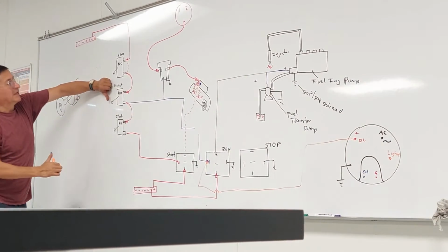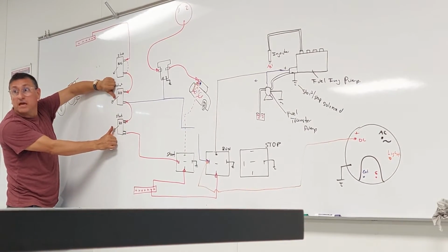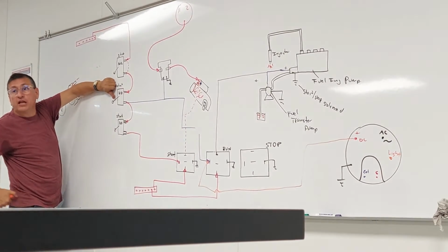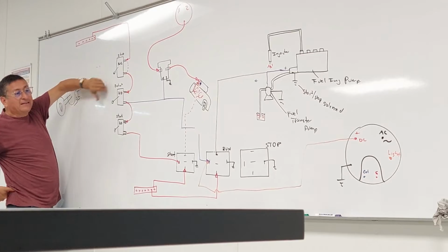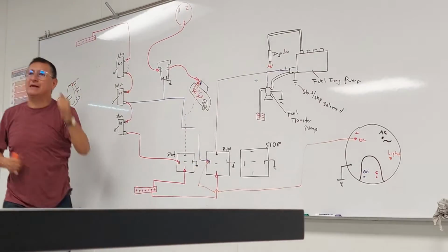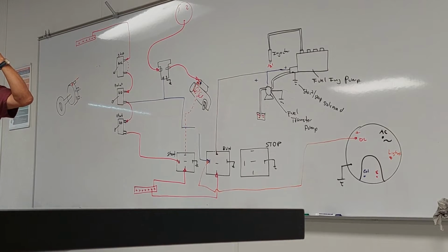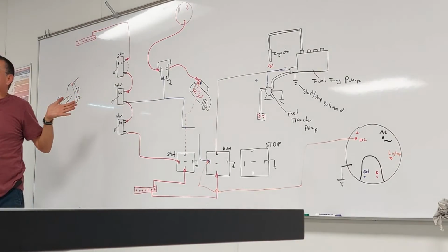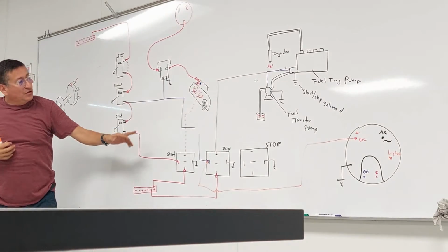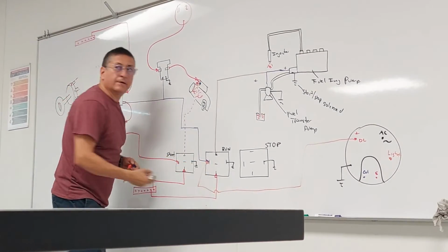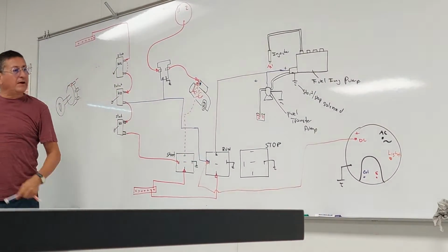Okay, look at this. Press, press, follow me. Press, press, crank, and the engine starts. I remove that one, the engine continues running. 10 more seconds, I remove this, and the engine continues running because I have power over there. Bingo, the engine is running. You like that? Yes. That's simple, no? And you use those relays, start relay and run relay. Pay attention. I have a question.